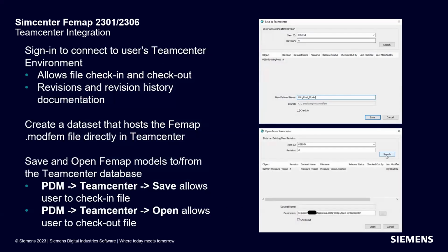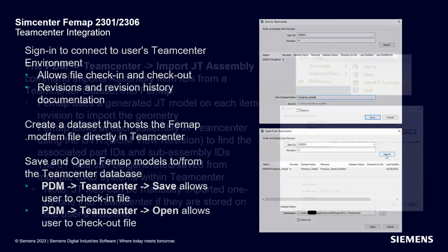So you can sign in, connect to the Teamcenter environment. You can check in, check out. You can do revisions with revision history documentation. You can create data sets that host the Femap .modfem directly in Teamcenter, which you could not do before. And you can save and open Femap models too from the Teamcenter database using the save and open functionality.